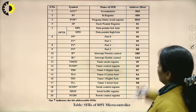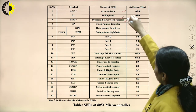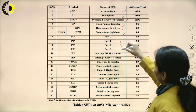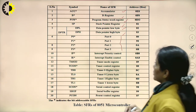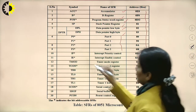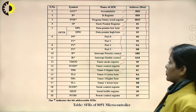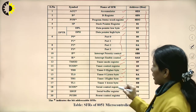As we can see here, accumulator, B register, program status word, stack pointer, that is SP, data pointer, that is data pointer low and data pointer high, 4 ports, P0, P1, P2, P3. These are all special function registers and these are their corresponding addresses of location. Next is interrupt priority control register. Next, interrupt enable control register. Timer mode register, timer control register. Timer 0 higher byte, timer 0 lower byte. Timer 1 higher byte, timer 1 lower byte.